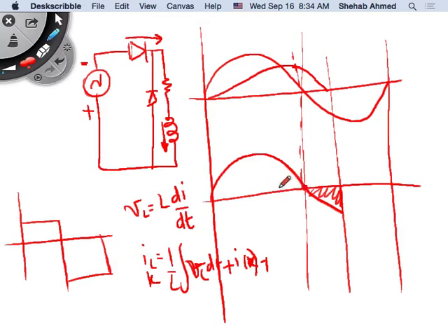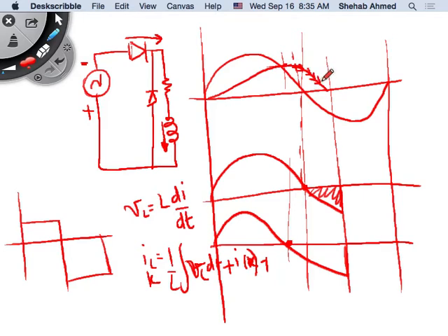So it's actually a little bit earlier than that, right? We said that this is the output voltage. Inductor voltage was, I think somewhere here it was equal to zero, so a little bit before. So whenever the slope was exactly 0, beyond that I had negative voltage across my inductor, the current started to go down, right? So this source was actually doing what?